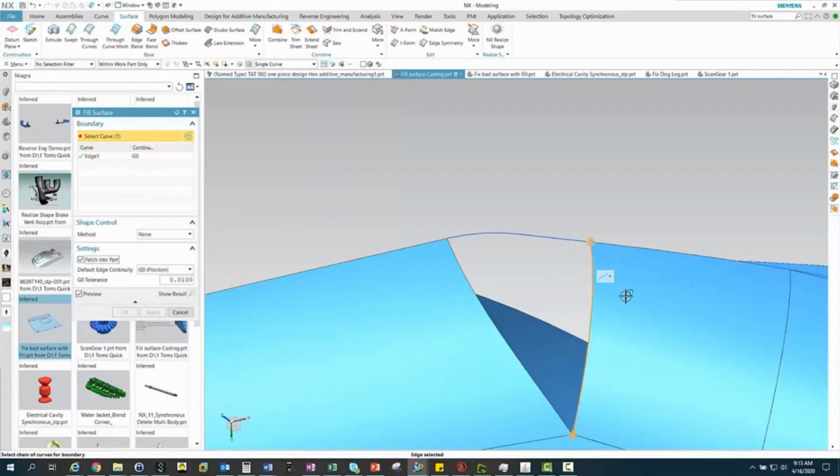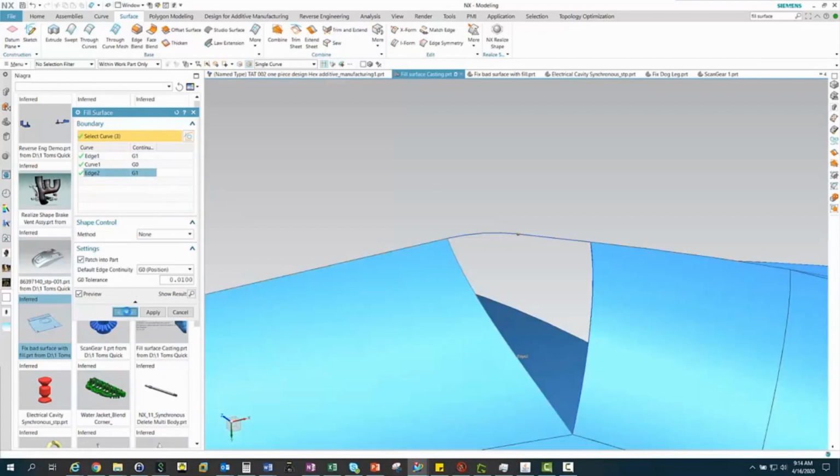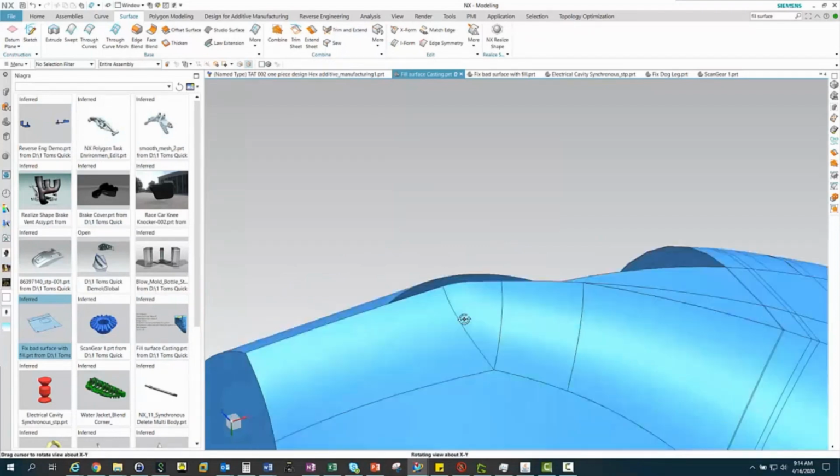Once I go and select it, you're going to see there I do have the ability to change that on the fly, also to G1 or G0, G2 or 3. I select my spline. You can see also within there, it lets me know if it's an edge or curve. Now you notice those asterisks. That's telling me, hey, that's an area that we've got to go in and add another curve or pick another edge or whatever. We come in there and now we can see we got our curve 1, edge 2. And if we want, go and make that a G1 also and say okay. And we put in our first face. So you can see there we went and patched it and cleaned that up.